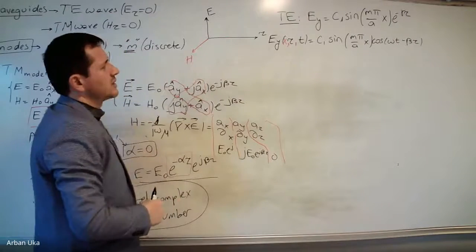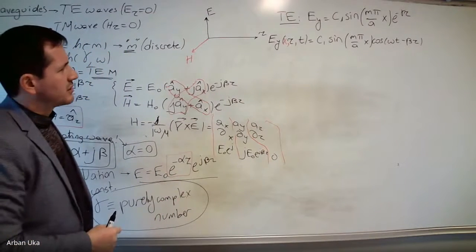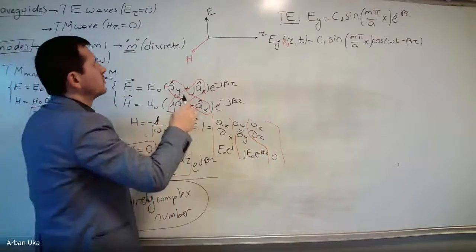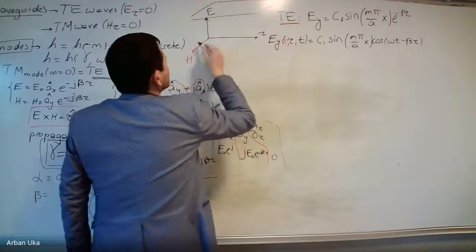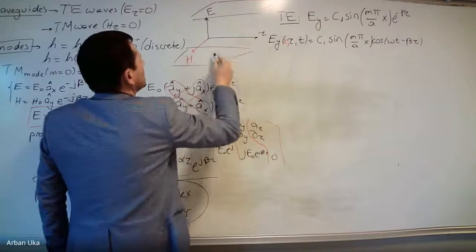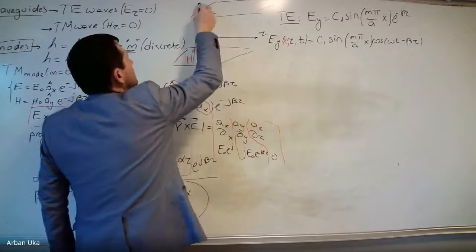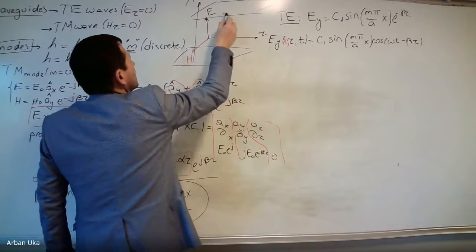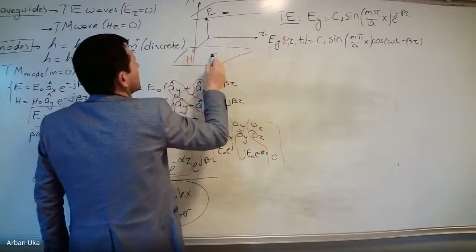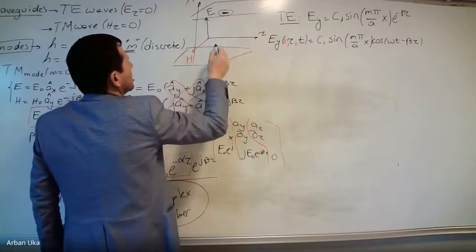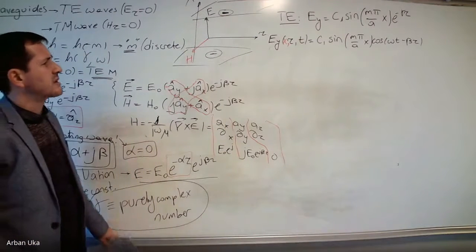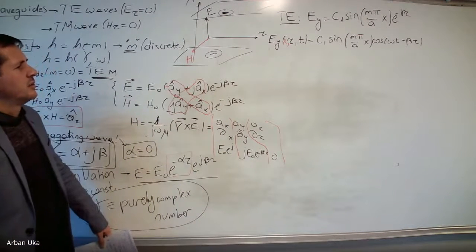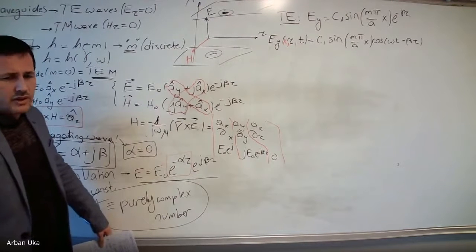But now that we need to satisfy also the boundary conditions, which means that if we have a waveguide that goes like this, assuming this is along the x, we want the electric field at the bottom part and at the top part often to be equal to 0, because we are discussing waveguides which are made of metal, made of conductors.